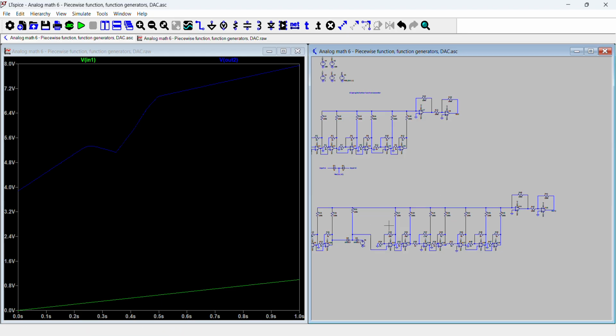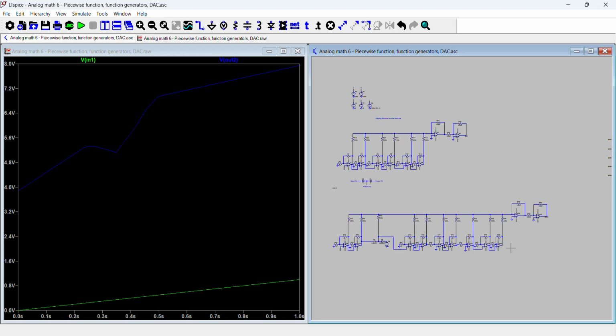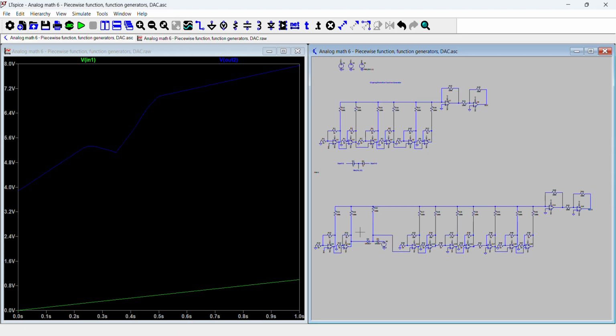However, as you can probably tell, it's really hard to design a circuit like this, because you have to decompose the different gain stages and figure out how to design them so that it adds up exactly to some shape. And it's not trivial to figure that out. So this is why this pure analog way to create universal function generators is rarely used in practice.